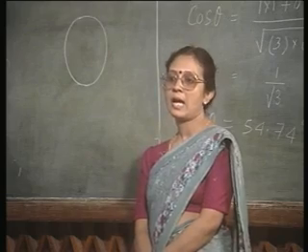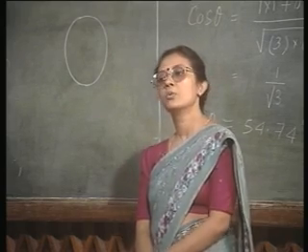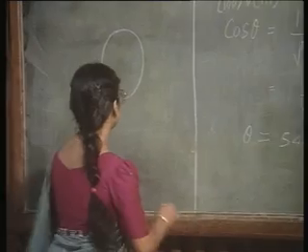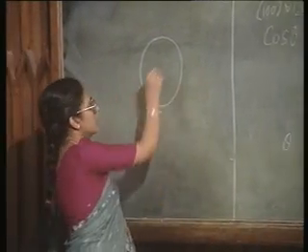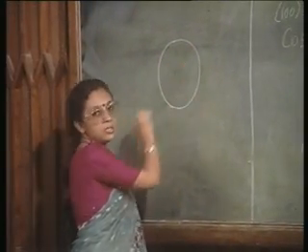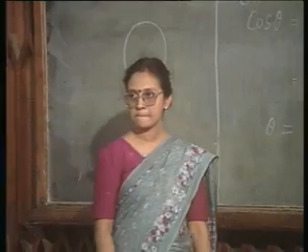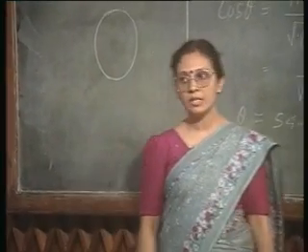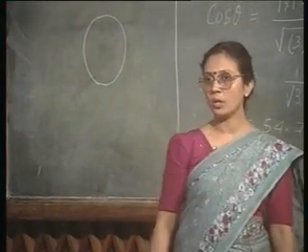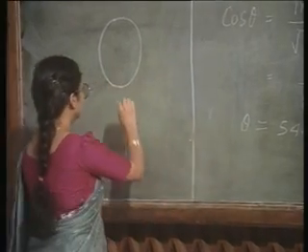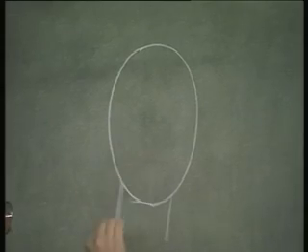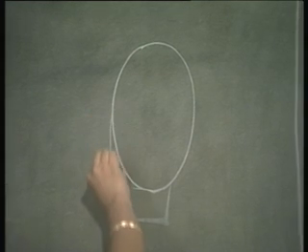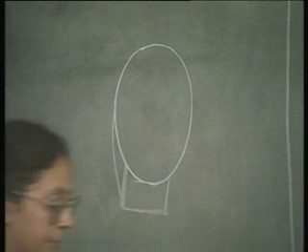If I have an 1 0 0 wafer, let us say that this surface is actually 1 0 0, and when I am cleaving, I am going to expose 1 1 1 planes here. The plane that I am going to expose here is actually going to be 1 1 1.